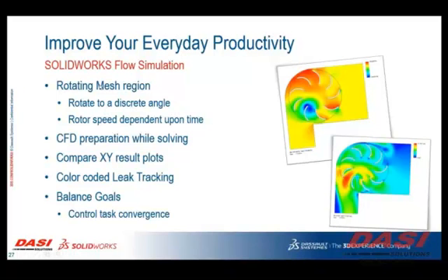One is called a rotating mesh region. Now in areas where the flow is created by something that's internal to the fluid itself, in this case an impeller or an involute, we've always been able to simulate those, but the part itself had to have some representation. This one here is creating the flow, so we'd have to put some turbulent type of value in there and some mass flow rate in order to simulate what it would generate as a real part.